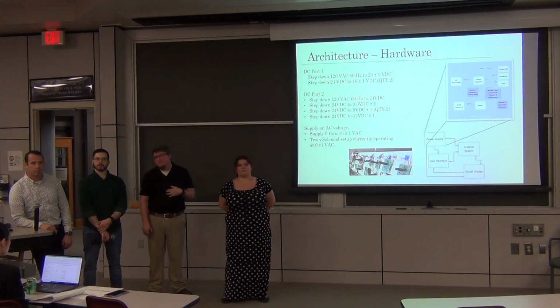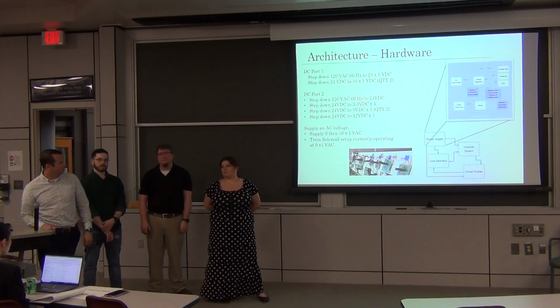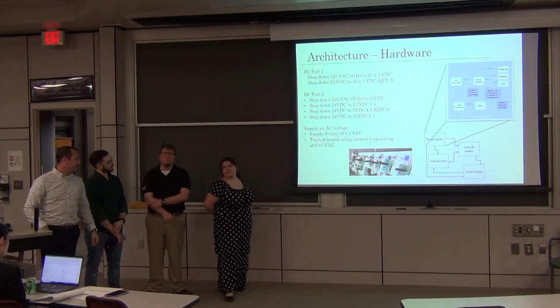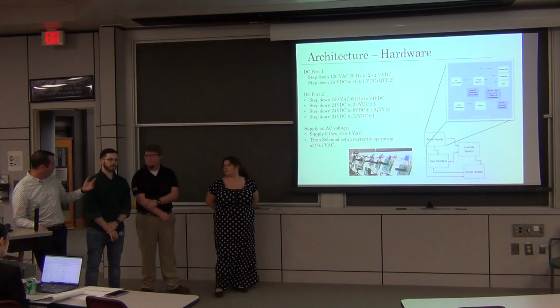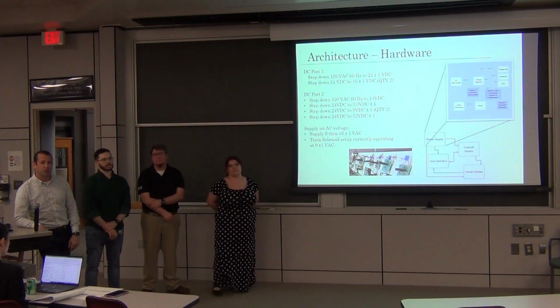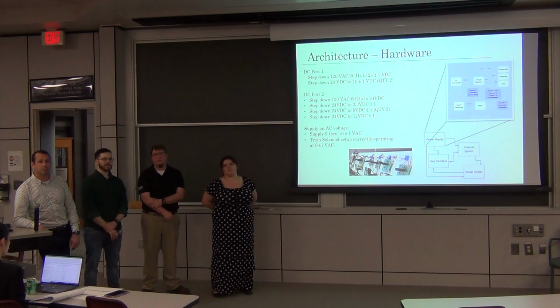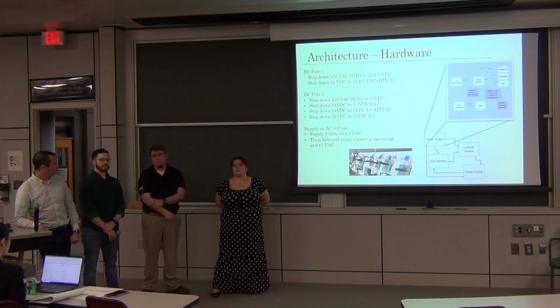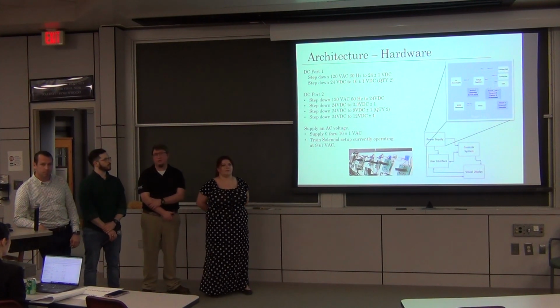Was it like a transformer? Yes. In fact, you can see it right here. After going through the spec sheets and discovering through trial and error, because we didn't have the exact specs of the solenoids, we were able to use a standard doorbell transformer from a house. It's cost effective and gives us multiple voltage levels, because the solenoids did not have a spec sheet either. So it was trial and error essentially.